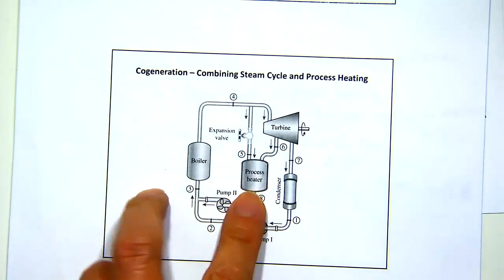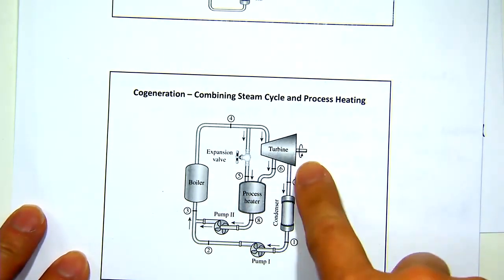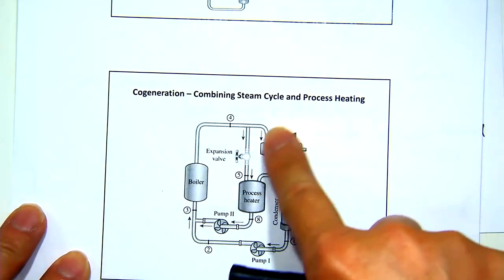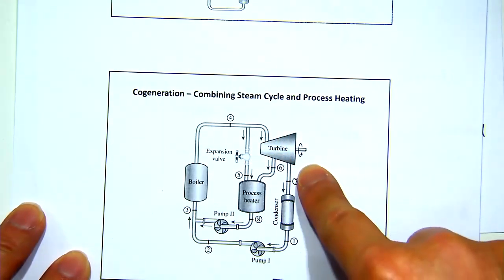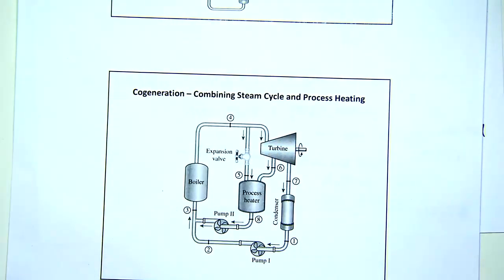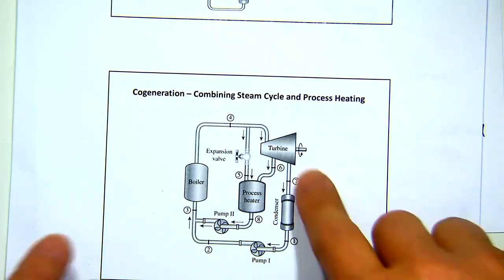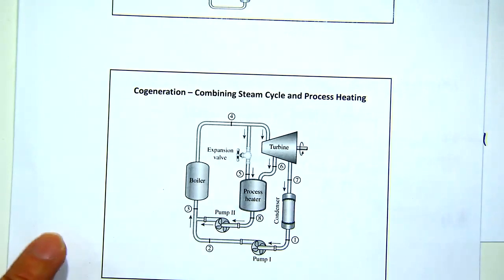So what's happening here is basically that all the thermal energy goes fully through the turbine. That amount of heat is being converted to work. That part of the conversion has the lowest efficiency, right? So by directing some for the process heating, you reduce the amount of heat that's being converted to work, right? So that's again related to the energy transfer from heat to work. That's inherently inefficient and is limited by the Carnot efficiency.